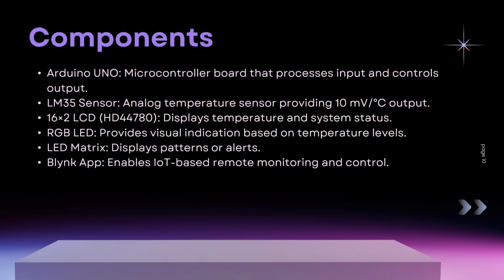The components used in this project are the Arduino UNO microcontroller board, which processes input and controls the output; the LM35 sensor, an analog temperature sensor providing 10 millivolts per degree Celsius output; and the 16x2 LCD, HD44780, which displays temperature and system status.